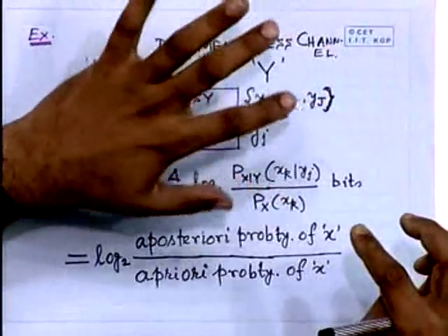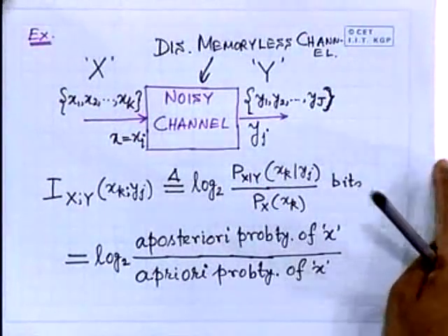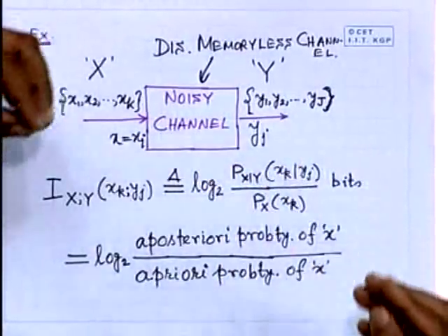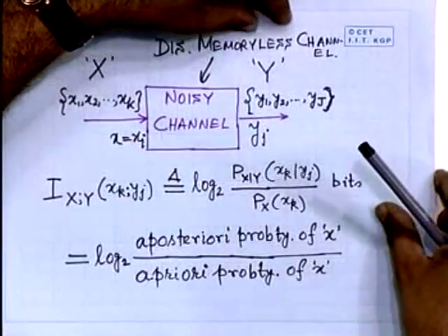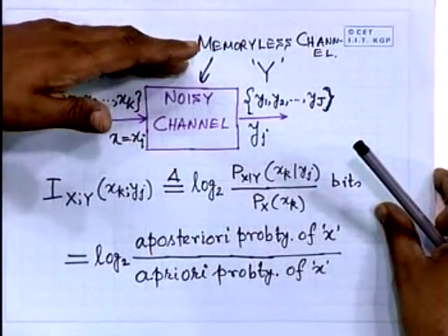There was the third example, say a point to point communication system through wireless. Usually there is no reason why the channel should remember what has gone through it, unless there is some design problem in the transmitter and receiver front end. So usually many of the propagation channels should behave as a noisy memoryless channel, but the channel may have some partial memory either because of lax design or because of the fundamental nature of the propagating medium that has been chosen. So the discrete memoryless channel is a good one, easy to understand, and is applicable also in usual cases.